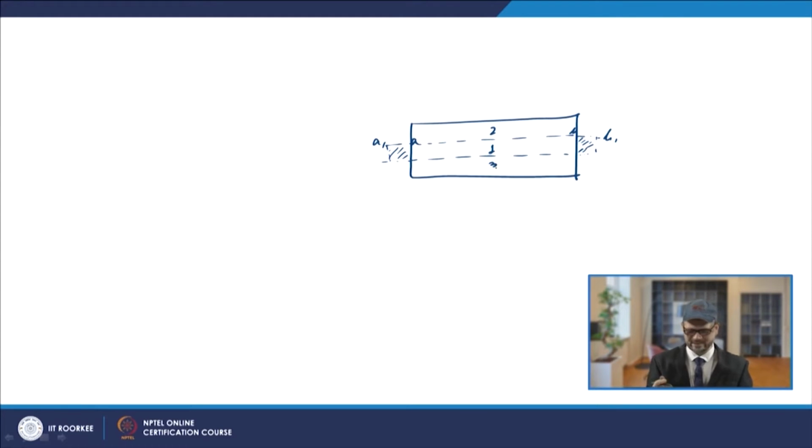Since zones 2 and 3 are not hot, they provide that restraint on zone 1. Accordingly, zone 1 will be under compressive stress, which is why we denote it with the negative sign.